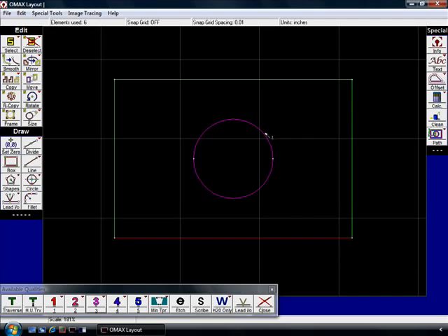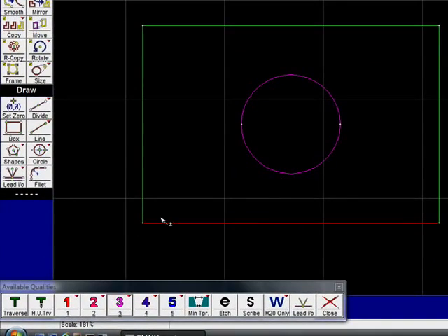So this will cause it to cut a little bit slower in this area, but the end result will be a smoother, higher tolerance surface finish. Then on the remaining pieces, I might make them quality of 2 because they just need to be cosmetically nice looking, don't have to be high tolerance, but we don't want to waste a lot of time on those. So you can optimize your tool path by choosing which areas for the machine to spend a lot of time on.